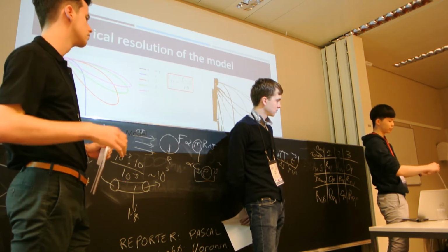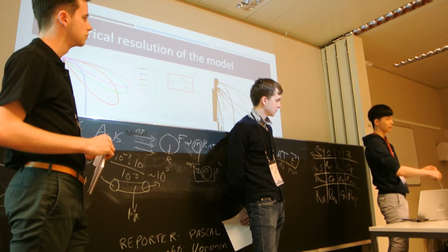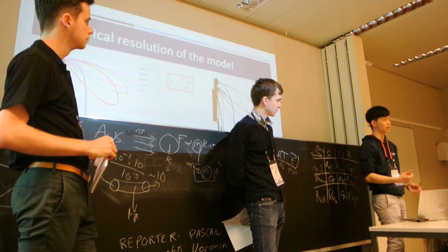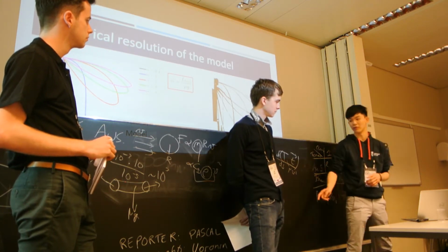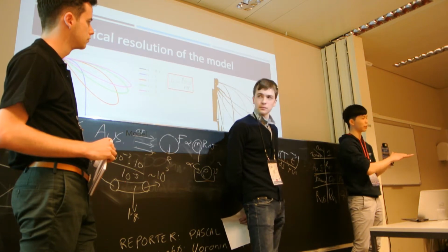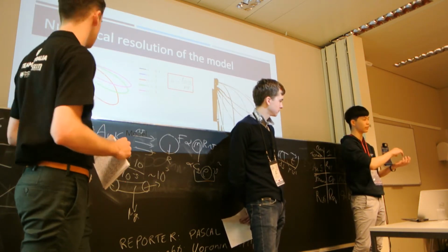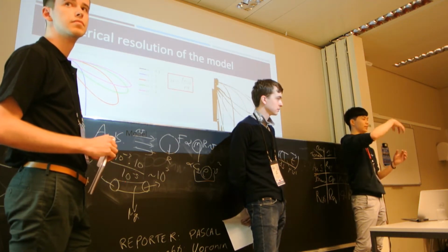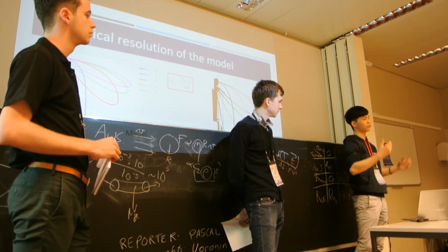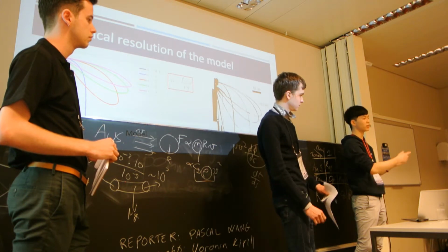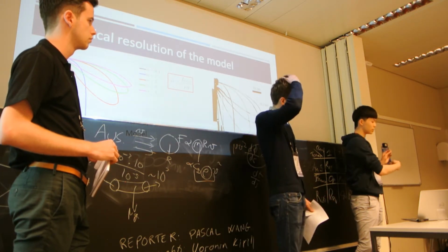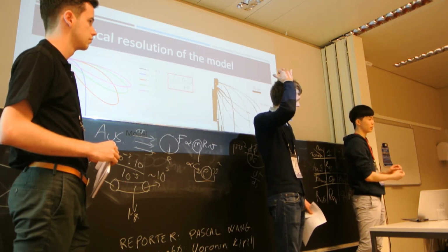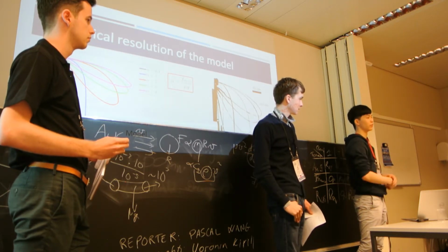repeatedly. At some point, you get fluffy strings coming out, and this will change the drag coefficient, because the drag coefficient is very dependent on the nature of the surface. If the surface is smooth, the drag coefficient is less. If the surface has strings coming out, then the drag term will change. So over time, the shape of the loop will change because of the deterioration of the string.